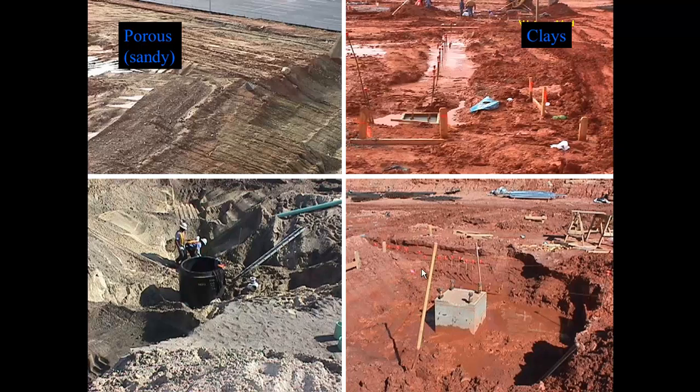So you can notice that in the silt and clay we don't have much of an angle of repose, and we'll talk about angle of repose here in a minute. So we can kind of cut right in there and it'll pretty much hold itself.